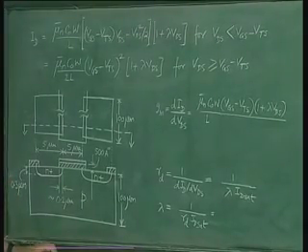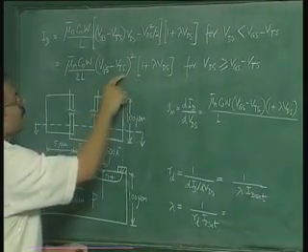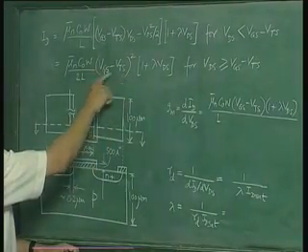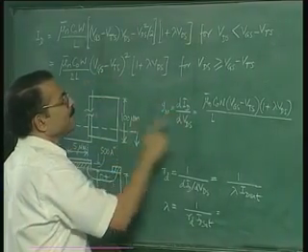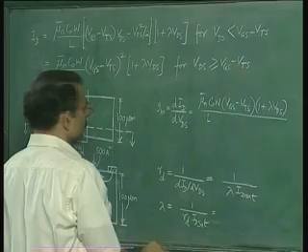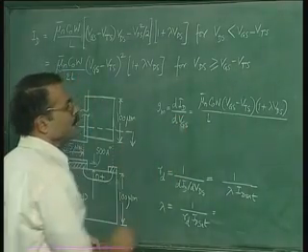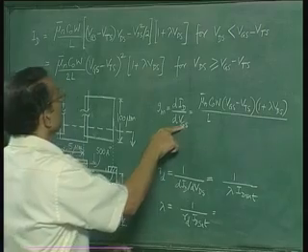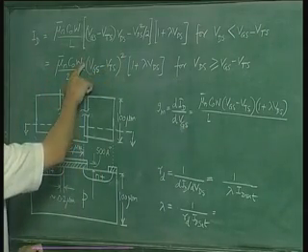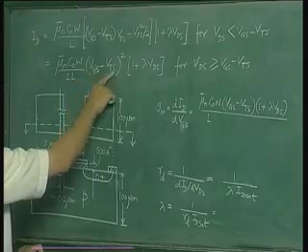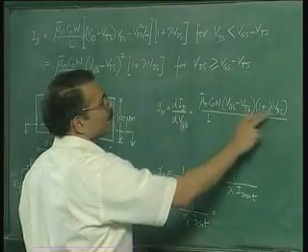Now what about the expression for transconductance? The transconductance expression is derived by differentiating this expression with respect to Vgs. So you see here gm is dId by dVds. This is wrong, it is dVgs. So when you differentiate this square law expression, you will get 2 here and you will get a linear term in Vgs minus Vt. So that is what is shown here.